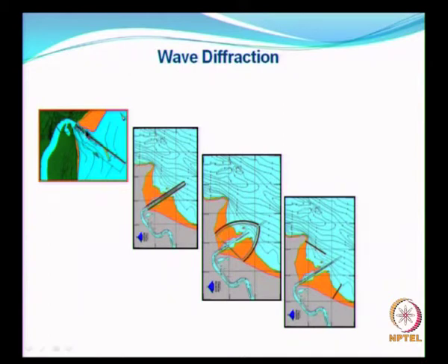So, can we have only one single breakwater, or can we go in for two breakwaters like this, allowing the vessels to move in? Then you find out the diffraction through the breakwaters and arrive at the wave energy. Or, because you want some more area, can we have two curved breakwaters like this, or two breakwaters as shown here? So for a given location you have different kinds of configuration which you can examine.